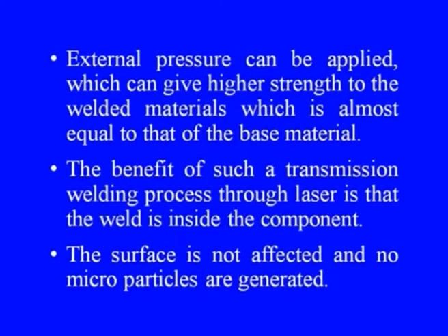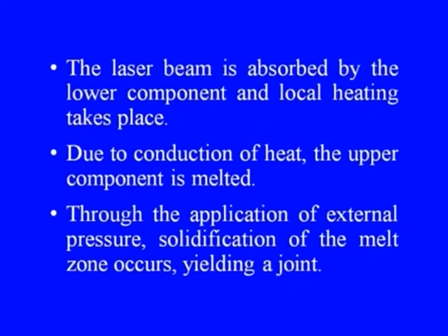The benefit of such a transmission welding process through laser is that the weld is inside the component. This is very important, that it is not exposed to the environment, and outside we cannot see anything. The surface is not affected and no microparticles are generated in the joint.